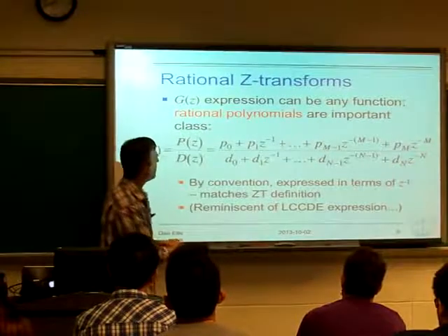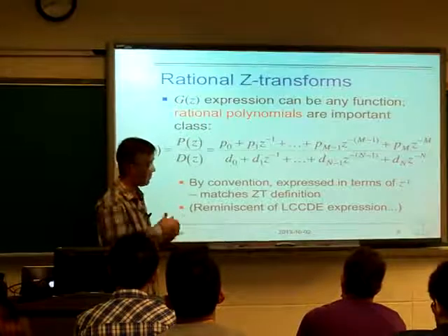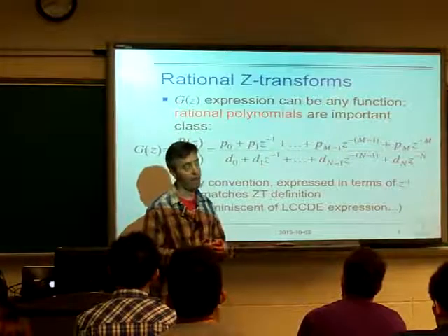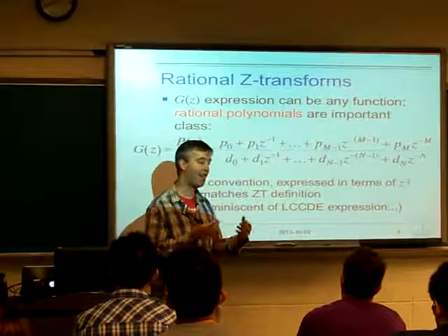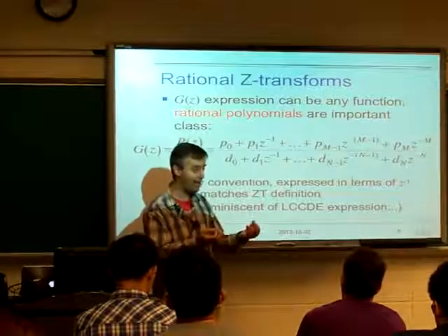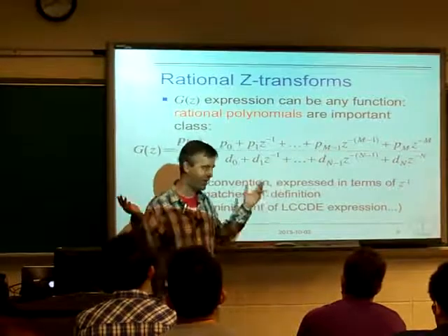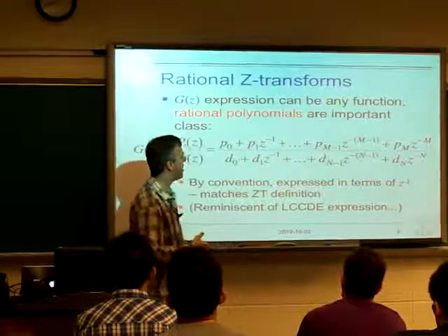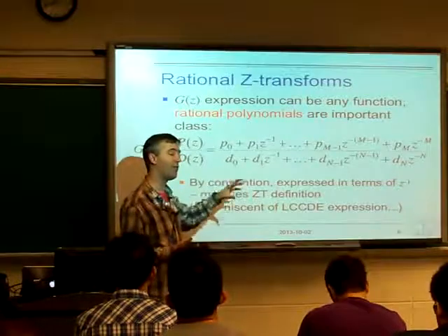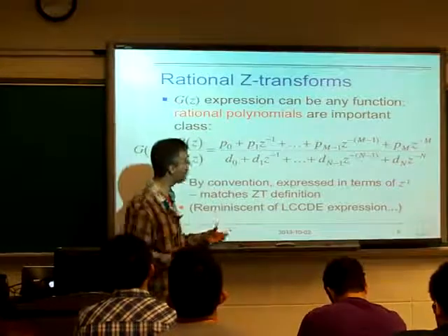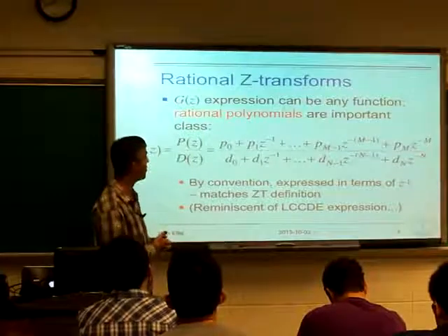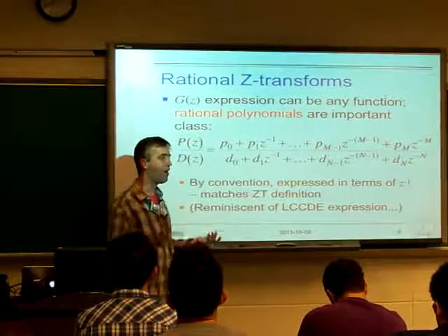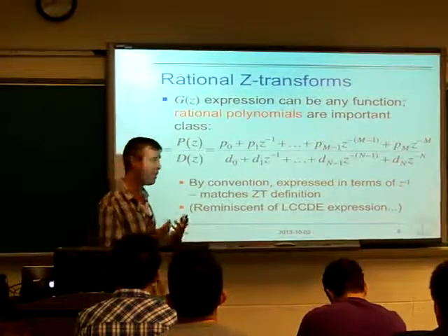Okay. So these Z transform expressions, the ability that we can work out these closed form expressions obviously makes this whole thing useful. If we had this, we could define a Z transform, and you could evaluate its value, but it's like this long, infinite sum or something like that. That wouldn't be very handy. But it turns out that very often we can get these closed form expressions for the values of the Z transform within the region of convergence that work out to be these polynomials, or in particular rational polynomials in Z, which then are things we can handle and things that have nice, well-behaved properties.